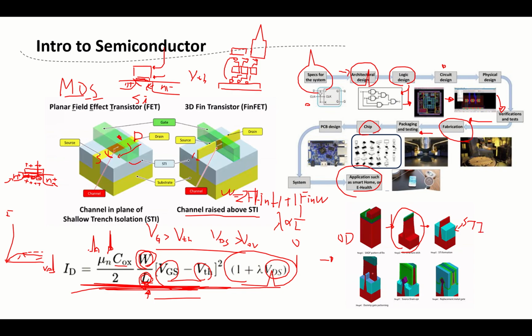And then we start using photolithography and also etching to make what we call poly. That's a gate, but it's not the real metal. So far we just make a poly gate to first define the gate and how high this is.